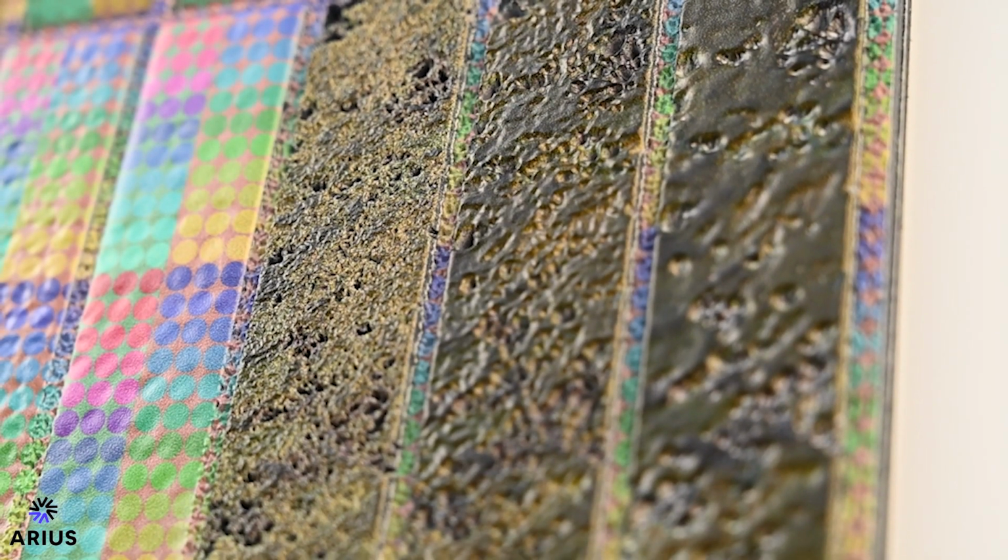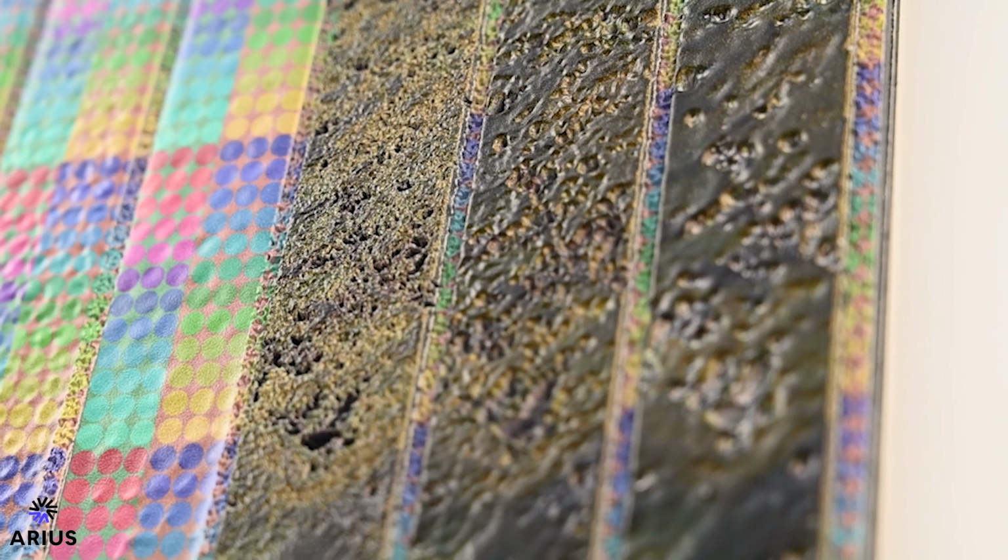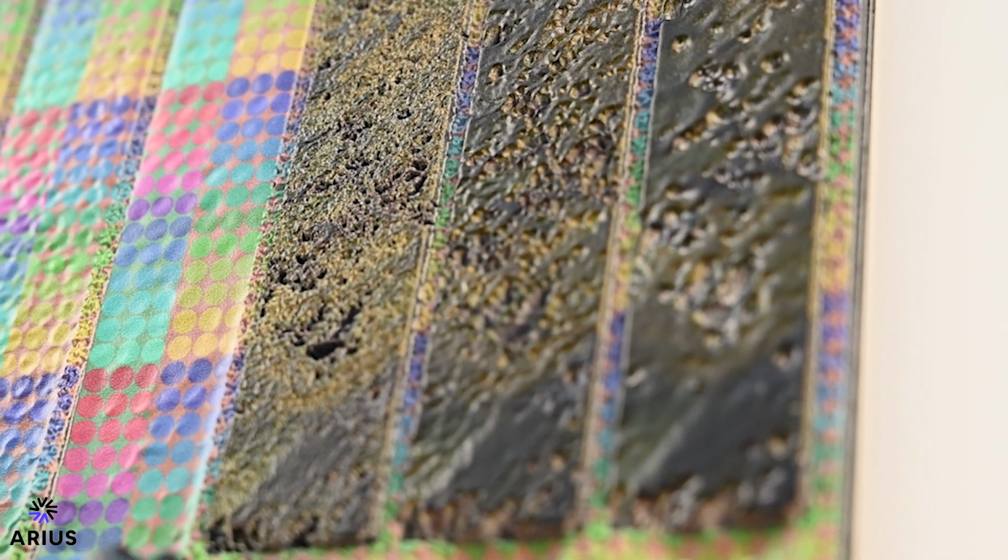Here are 3 identical images of a tree against a pale blue sky. Each column is 260 pixels or 2.2 centimeters. In the left column, the high contrast grayscale dark leaves and light sky elevation map results in black walls and a noisy surface. High contrast in the grayscale image over a few square millimeters can create an elevated spiky noise effect when printed. To remove this, blur the noise level pixels or lower the contrast on those small details.